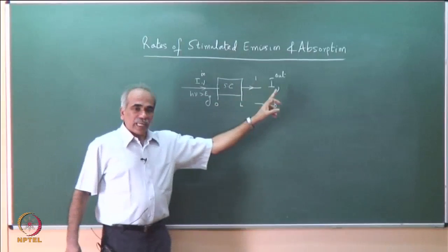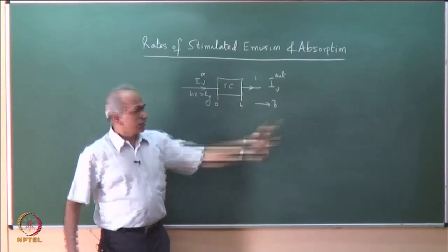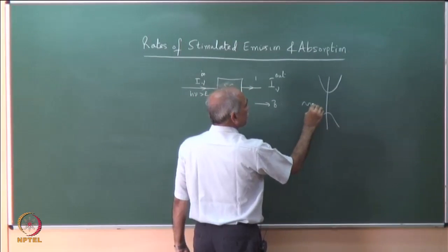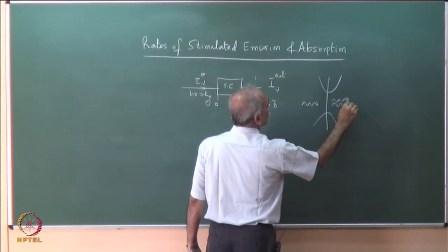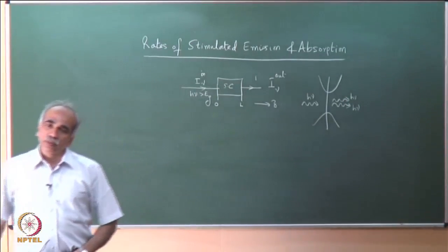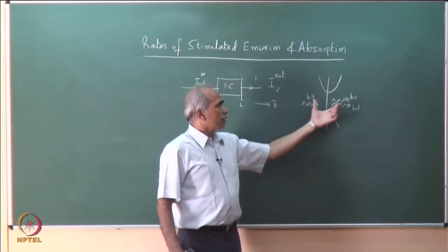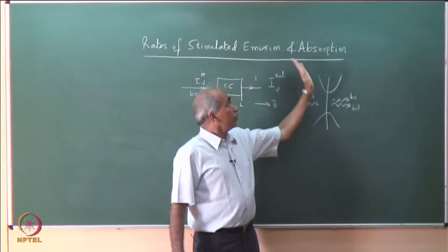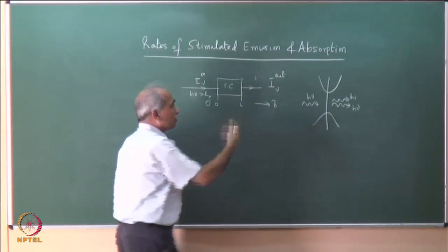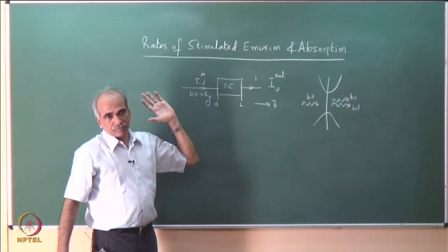So, if we are looking at amplification, amplification can take place only by stimulated emission, because that is the basic process of amplification, where one photon incident here leads to generation of two photons in simple terms. So, h nu here and gives out. So, this is a process of amplification. Amplification refers to coherent amplification. So, stimulated emission is the one which is responsible for amplification. By the process of absorption, the photon can get absorbed and the output can get diminished or attenuated. So, we want to find out what is the coefficient of gain or coefficient of loss in this semiconductor. That will be our objective.